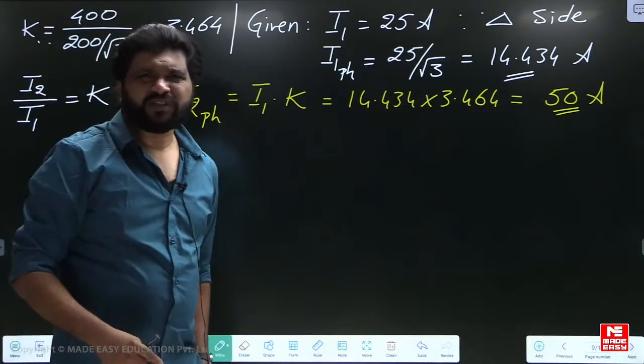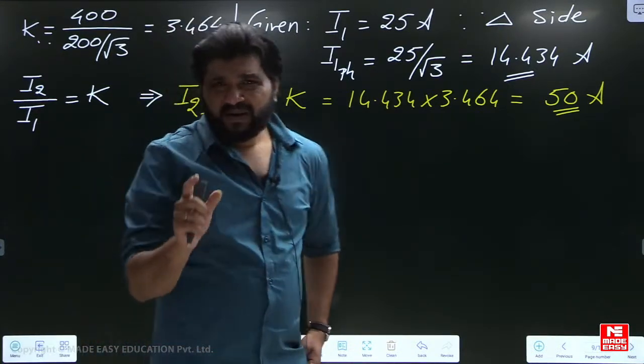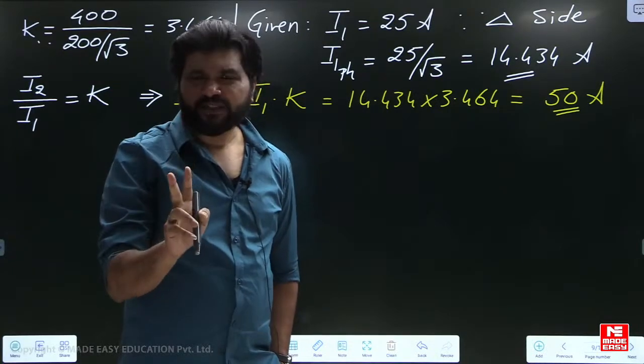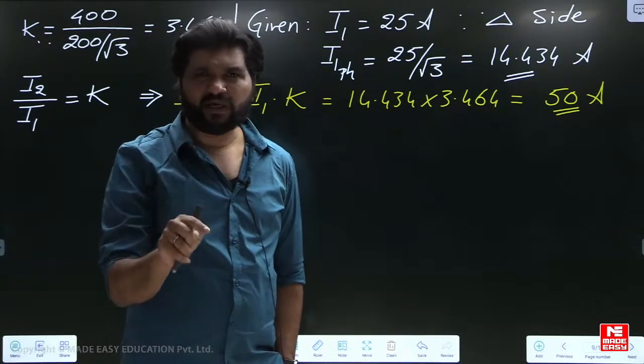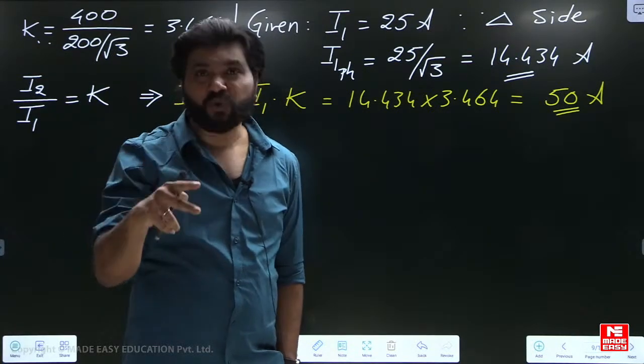So if you read this question, it is establishing a torque of 25 Newton meters when it is blocked. That is very clearly given. So we'll go back to the torque formula which has R2 in it.